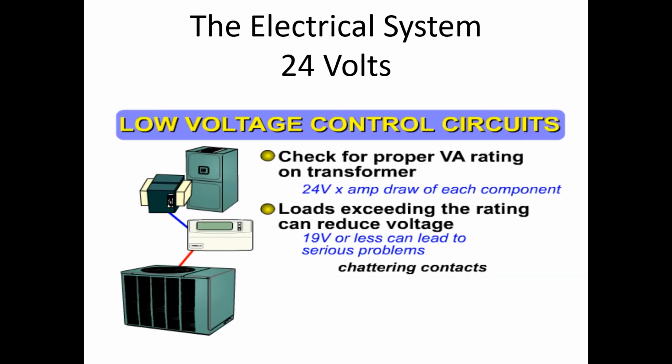19 volts or less can cause serious problems with our low voltage components, specifically our contactor. We can have contactors chatter, and that chattering can lead to a pitted contactor. The other thing it can do is cause numerous failures with the coil opening on our contactor.